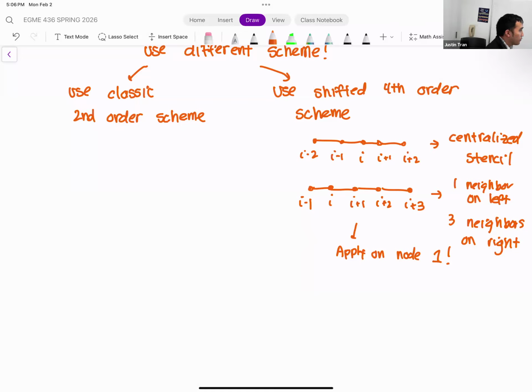It's the most straightforward to understand, because you often don't need more than one neighbor. And second order accuracy is already pretty good. It's usually not worth it to go 4th order or more. But I did want to talk about this, not that we're going to do anything with it. We're not going to be implementing any 4th order schemes. I don't even know if OpenFOAM can get up to 4th order accurate. But I did want to discuss this briefly, just to show you just how cumbersome it is to go beyond second order accuracy.